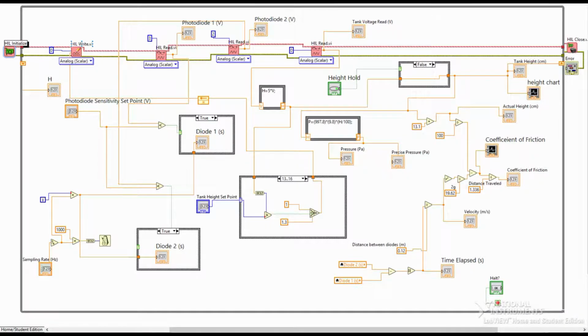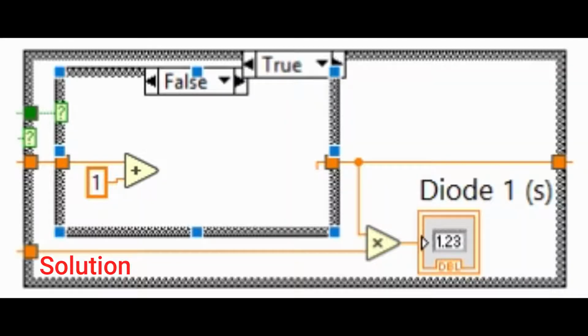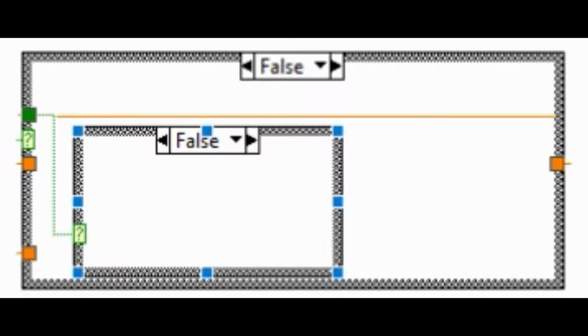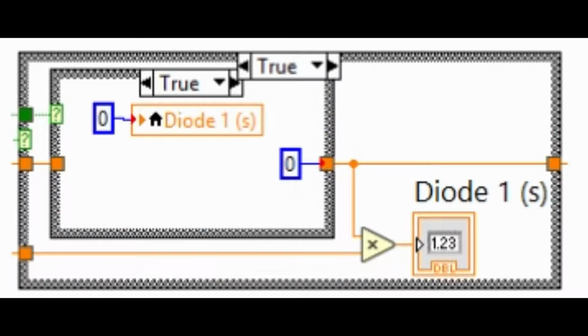As we found, slow speeds often broke our velocity detector by allowing it to hold on to values from the previous test. Our goal was to implement some sort of restart to stop and zero our timers. Now, when the timer is running and the button is not being pressed, a value of 1 is being added to the shift register for every iteration of the while loop. While the timer is not running, no values are being added to the shift register.